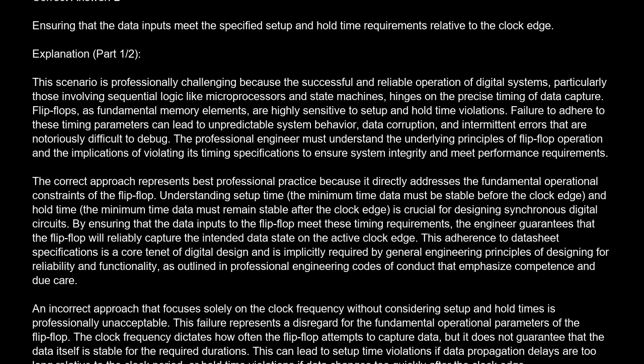An incorrect approach that focuses solely on the clock frequency, without considering setup and hold times, is professionally unacceptable. This failure represents a disregard for the fundamental operational parameters of the flip-flop. The clock frequency dictates how often the flip-flop attempts to capture data, but it does not guarantee that the data itself is stable for the required durations. This can lead to setup time violations if data propagation delays are too long relative to the clock period, or hold time violations if data changes too quickly after the clock edge.